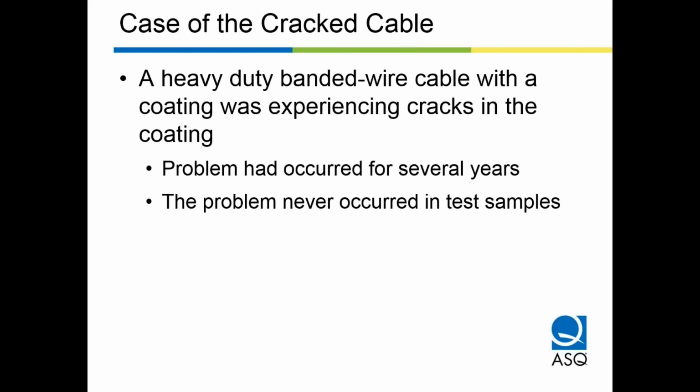Update relevant documents. That's shorthand for update your failure modes and effects analysis. Update your lessons learned if you have a lessons learned database. Maybe you need to update your control plans. If you're in engineering, update your design rules. Use the knowledge, you paid for that knowledge. If you've spent months working on a detailed root cause analysis, you really paid for that knowledge. Get something out of it. Make sure that failure doesn't happen again in 5 years.